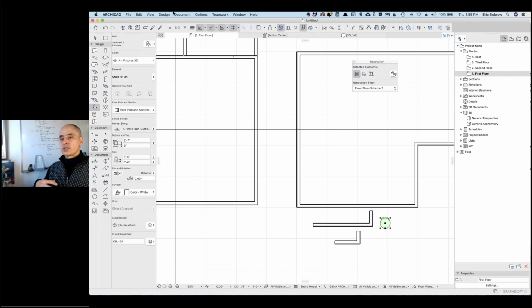Now, we're going to take these sort of arbitrary grids and talk about using them for a construction purpose. Well, what do I mean? As you know, when you build with masonry, bricks or CMU, you often will want to have the wall of a building be a certain whole number of masonry units, and you'll often want to have doors and windows cut into it at the edge of a masonry unit. So while you can measure things and type in values, it's nice to have a grid that helps you with that. So let's just see how this works.